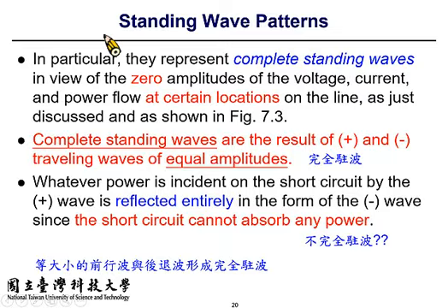If you have a resistive termination, and the resistance of your load is not the same as the characteristic impedance of the transmission line, what happens? Some of the incident energy goes into the termination and some gets reflected. So you will have a so-called partial standing wave. You will have V minus components.